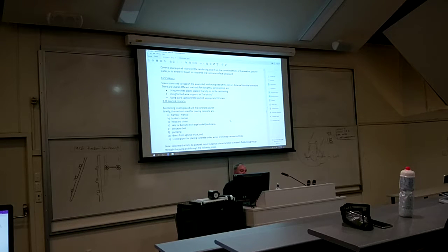So those are the sort of things that you need to calculate when you're doing your job. Is it easy to get in there? Can I get in there and work the concrete? Can we get a team of people in there before it goes off, or is it going to be too hard to do it? So if you're barrowing that concrete, that's going off the whole time while it's in the barrow, while it goes into place.